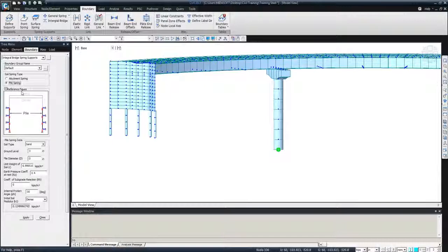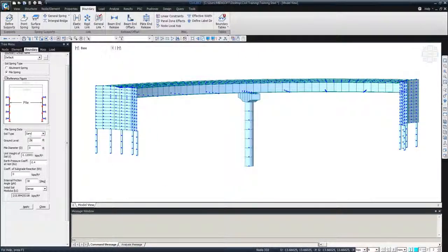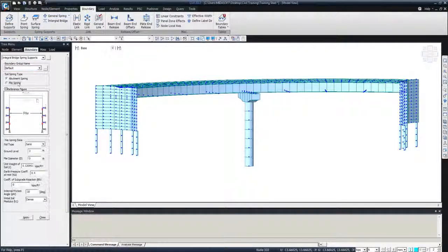You just need to fill in this information. The pile is quicker, so I'll do it for you. Here, for the type of soil, I assume that is sand. The ground level, I'm going to put in feet. I'm going to go with 28, and the diameter of the pile will be 1 foot. The ground level will be 28, and the pile diameter, and then 150 here.